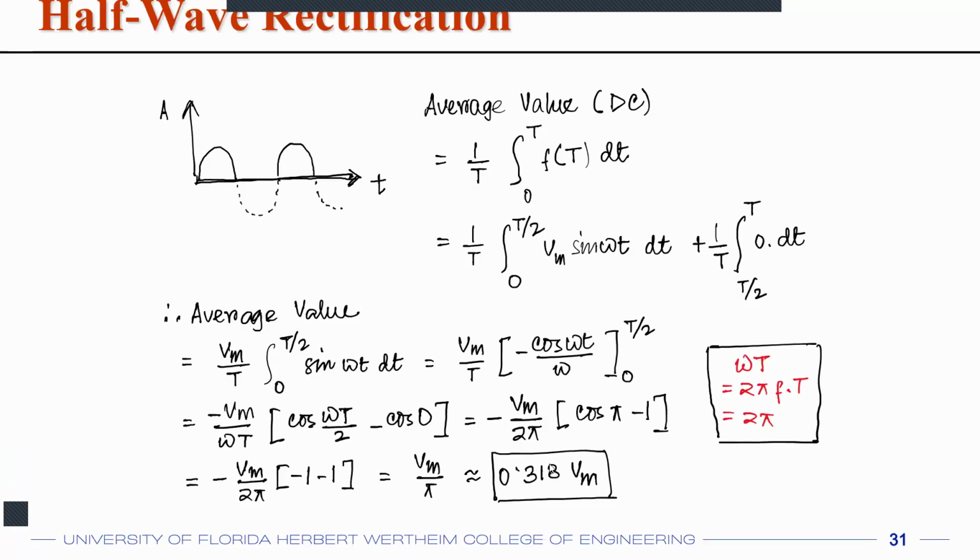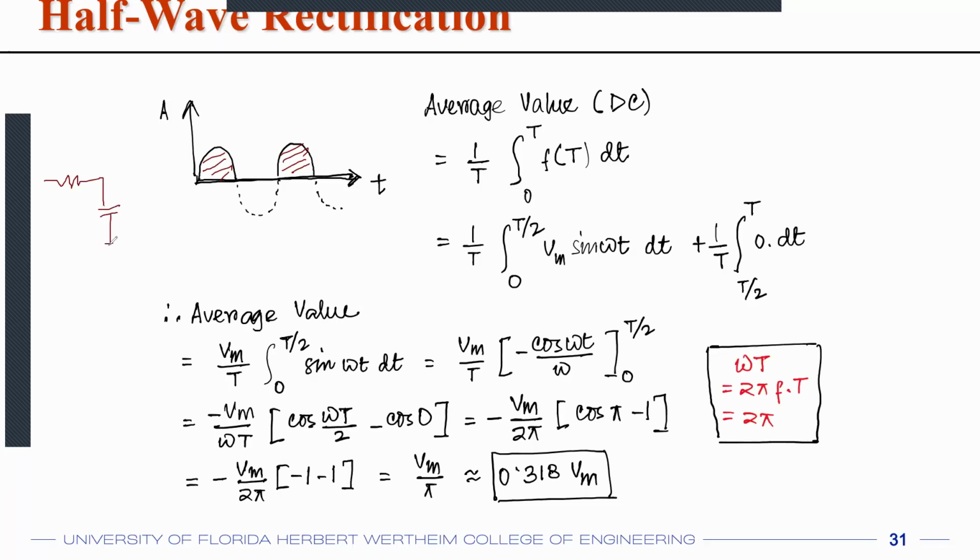Because this is non-zero, you basically have a DC signal now. There's one thing that I did not talk about: what you have after the half-wave rectification is just this half sine wave. So you have this part and you have this part. Now, how do you average this half dome-like signal? You just create an averaging circuit, or a low-pass filter. A low-pass filter is an averaging circuit. What a low-pass filter looks like is basically a resistance, then a capacitance to ground.